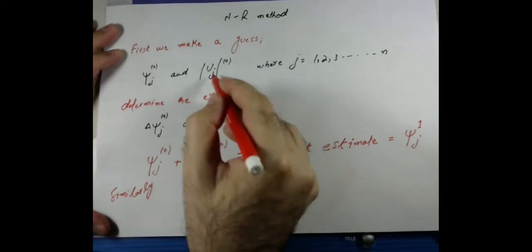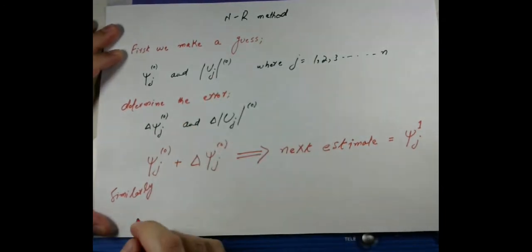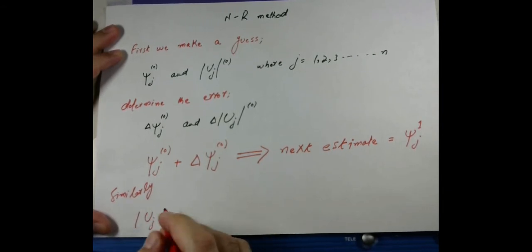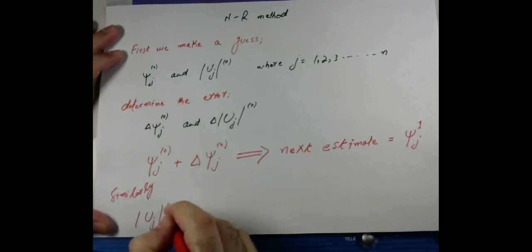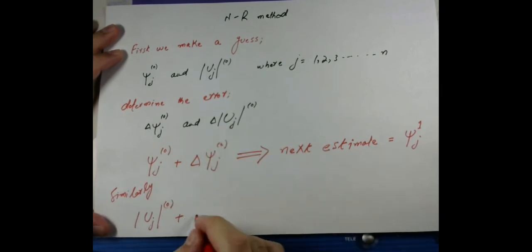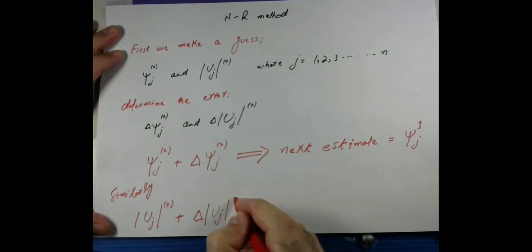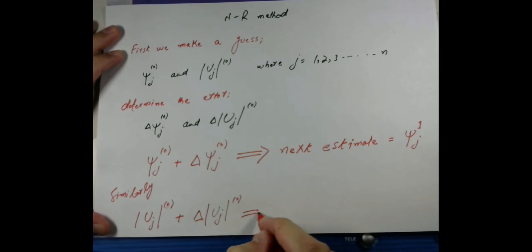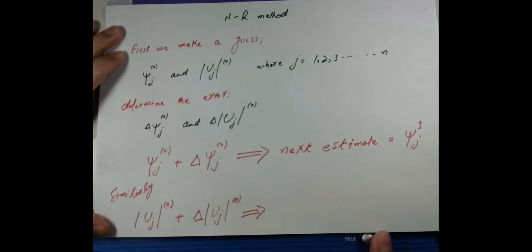So this is the guess, which is the magnitude of the voltage, plus the error in this first guess, which is delta uj 0. And remember, this is not the power, I hope you remember we discussed it, this is not the power, this just represents the iterations.